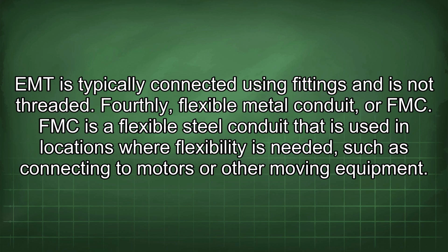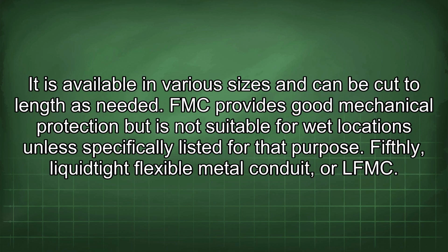EMT is typically connected using fittings and is not threaded. Fourthly, flexible metal conduit, or FMC. FMC is a flexible steel conduit that is used in locations where flexibility is needed, such as connecting to motors or other moving equipment. It is available in various sizes and can be cut to length as needed. FMC provides good mechanical protection but is not suitable for wet locations unless specifically listed for that purpose.